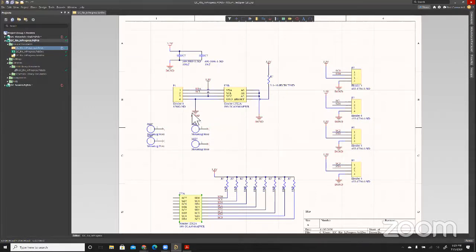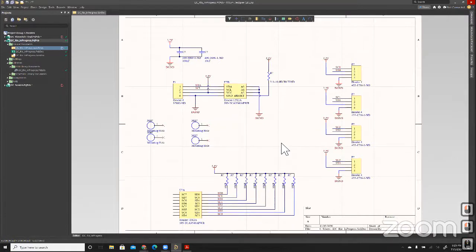And then you match your Robo-Rio I2C connection here. Something to be mindful of is that I noticed that on the Robo-Rio, it's the data line and then the clock. But for the JSTs, it's the clock and then the data. So that was something that I caught today while doing that, that I wouldn't have been paying attention to otherwise.